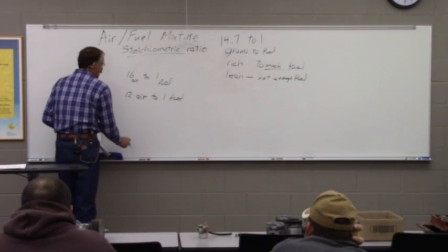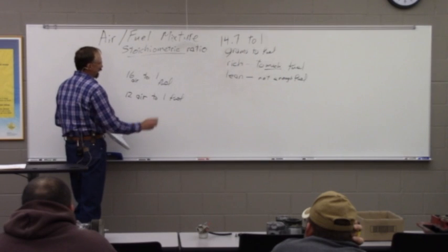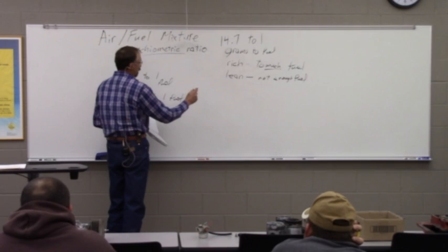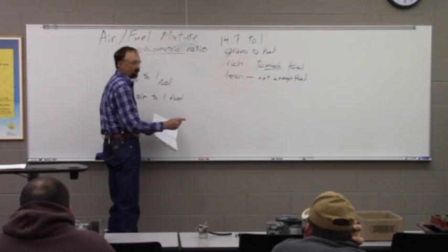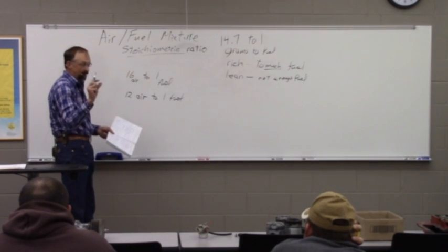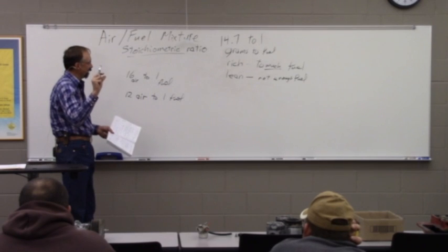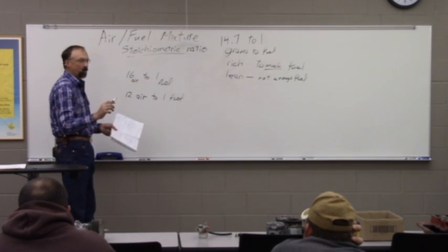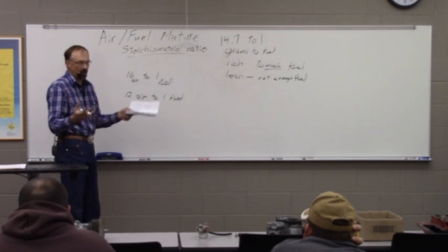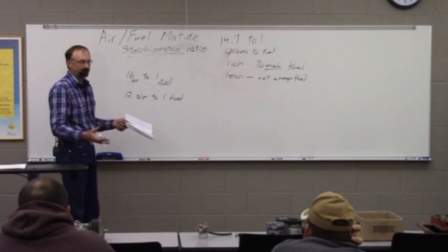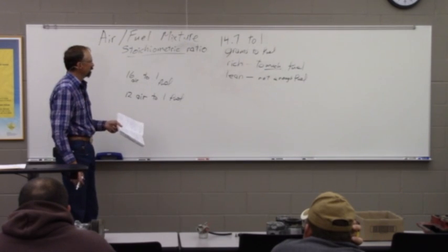Now, if we're unbalanced within reason, in that area where we're at like 14 to 1, it actually will make good power there. It'll make slightly better power, just barely, and it's easier to get it to burn when we don't have enough temperature, but it makes a little more of the undesirable side byproducts.